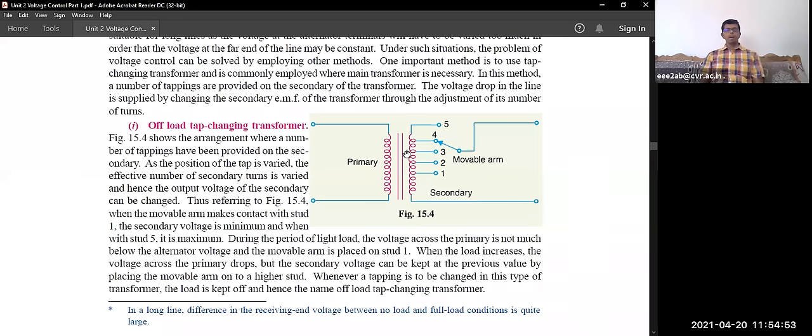Each area is connected via one feeder. And also sometimes, if you are staying near an industry, that industry will have a separate feeder. So if they open that feeder, that particular industry alone will be islanded. Like that also they may plan in the substation.